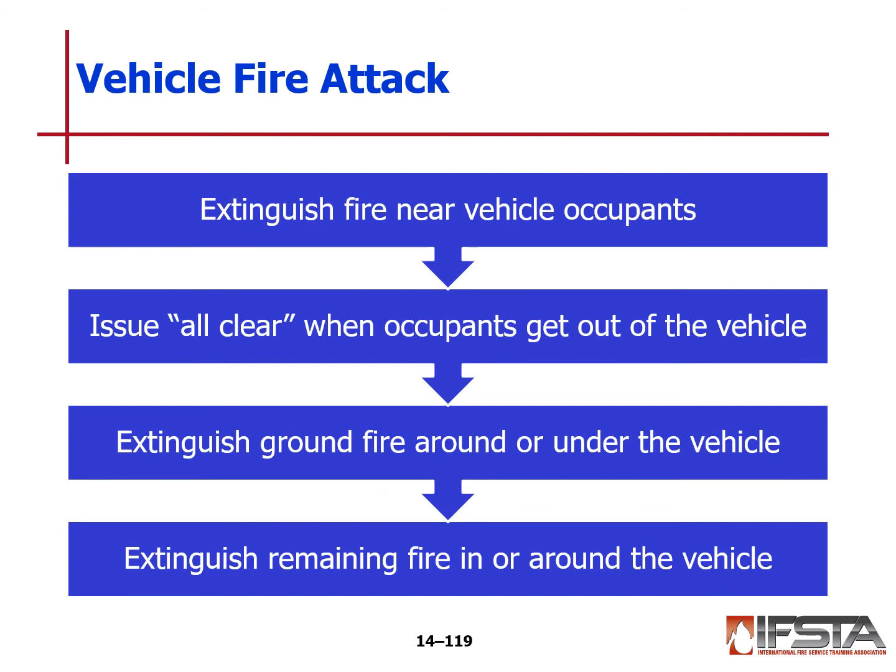Extinguish fire that's near vehicle occupants. If they're still in, that's our priority. Issue an all clear when the occupants get out of the vehicle. Extinguish ground fires around and under the vehicle as you approach, and extinguish the remaining fire in and around the vehicle. So this is kind of our priority steps.